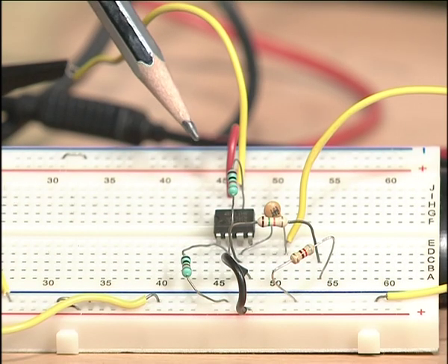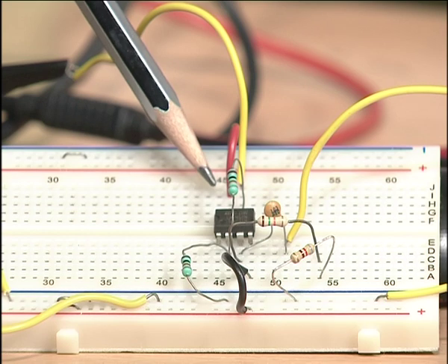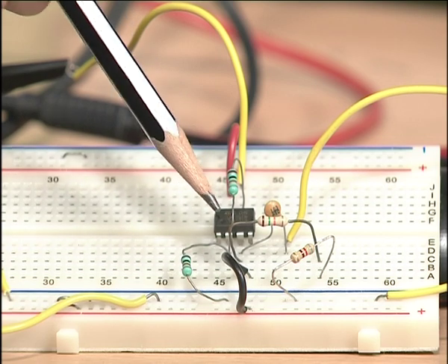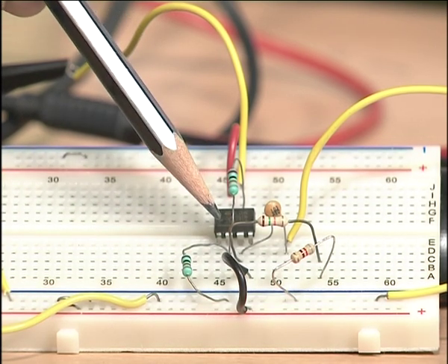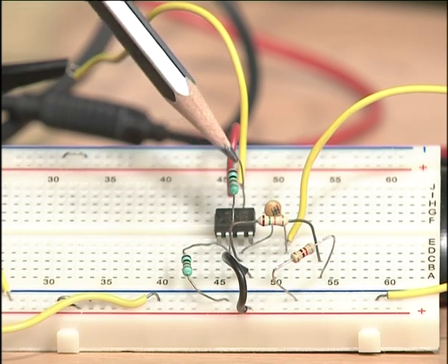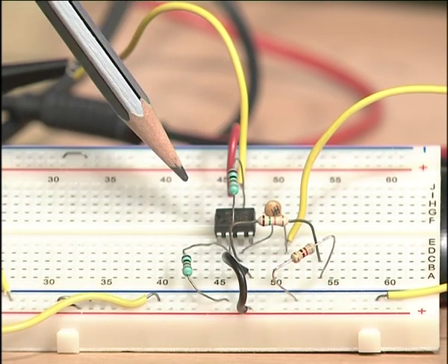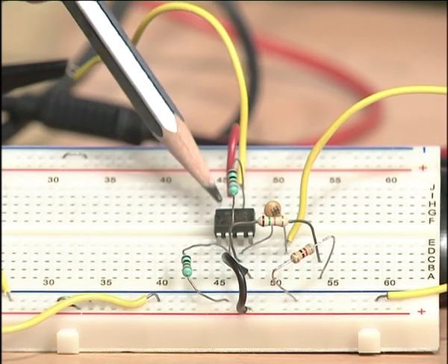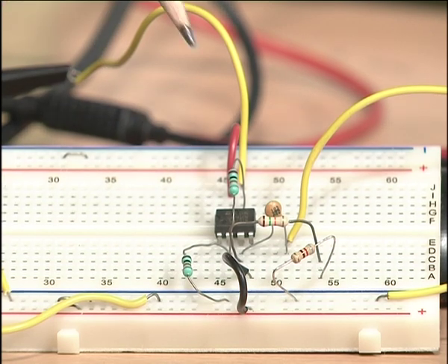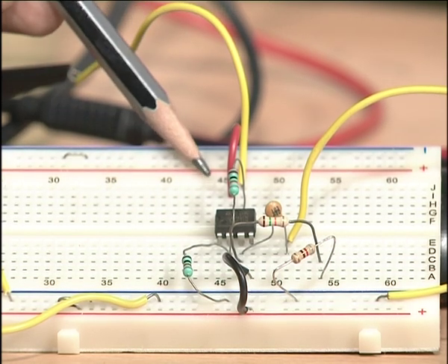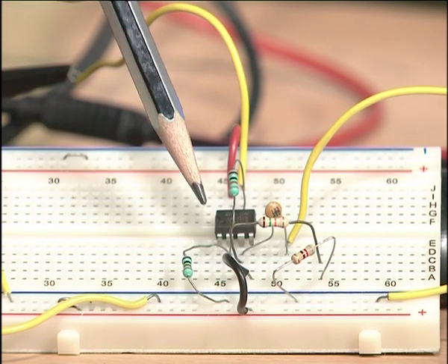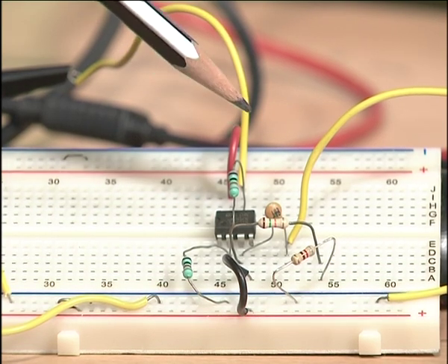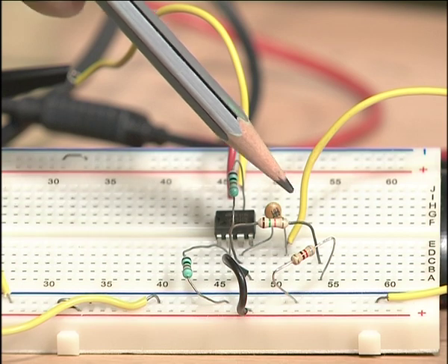Plus 12 volts is connected to the 7th pin of the IC 741 amplifier, and the negative potential, which is minus 12 volts, is connected to the 4th pin of IC 741. The pin configuration here is numbered with the notch here. The first pin is from here and then it goes on up to this end, which is the 8th pin. So, the 7th pin here is with the plus supply and the 4th pin here is with the negative supply.